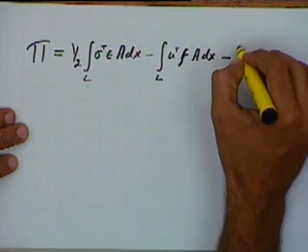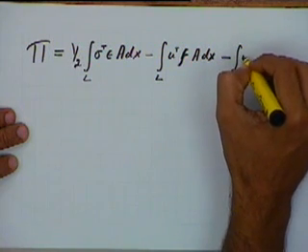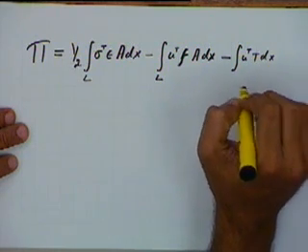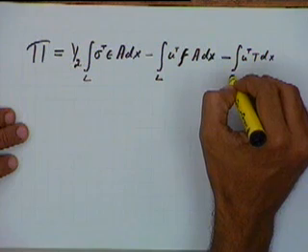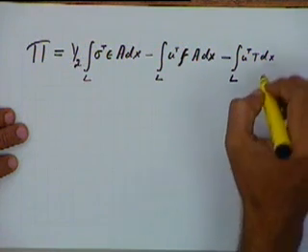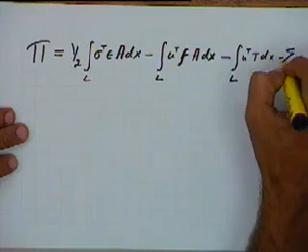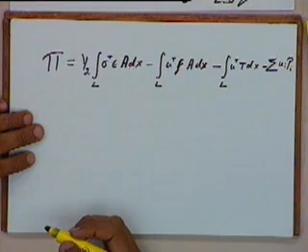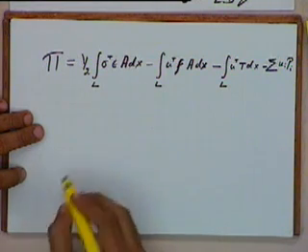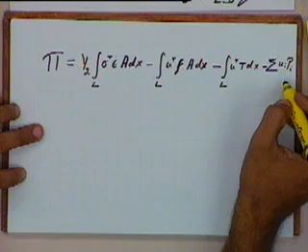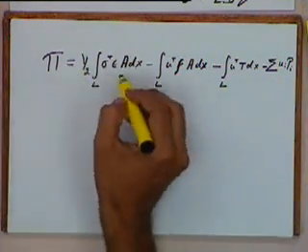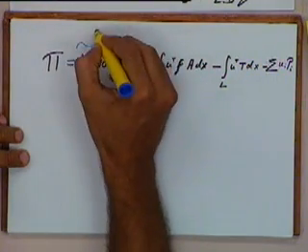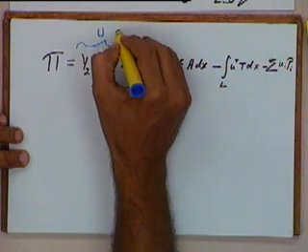Minus integral of u transpose T into dx. So again this integral will also be over the length of the element in this case, and minus the potential energy contribution because of the point forces, that will be sigma u_i P_i. So this will be the expression for the potential energy in this problem. This first term is what we call the strain energy U, or the strain energy.